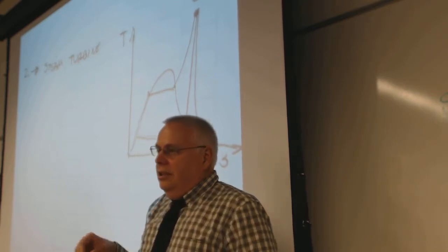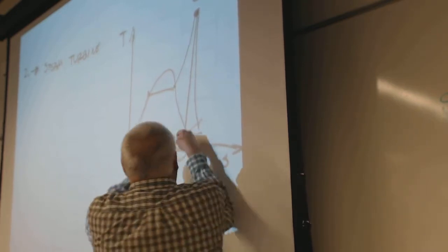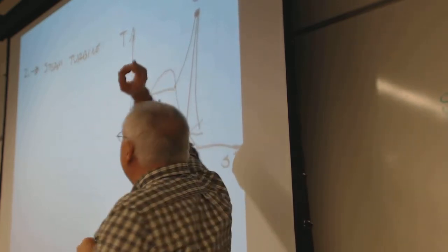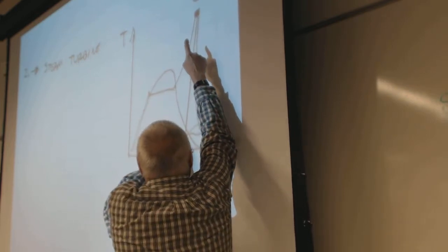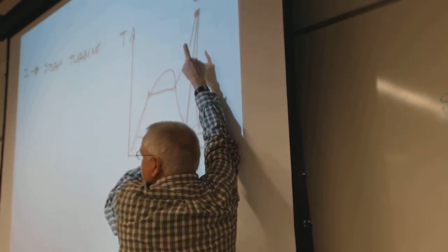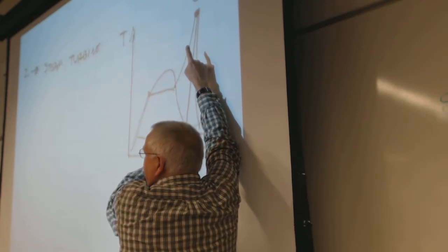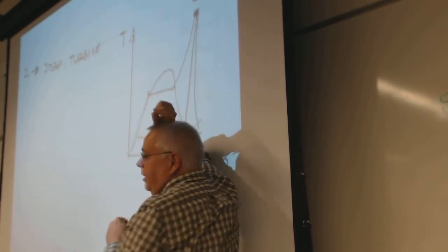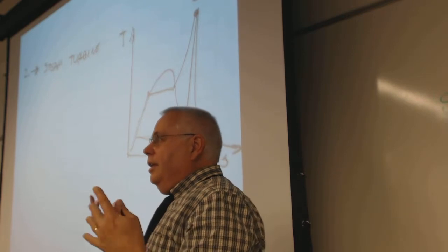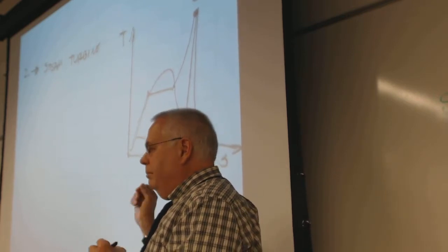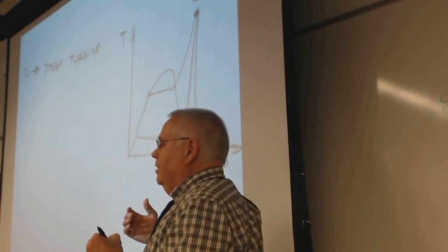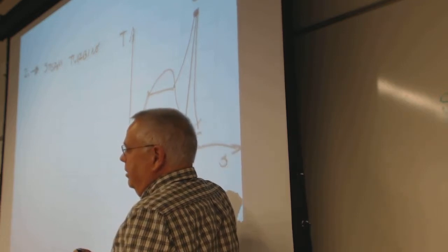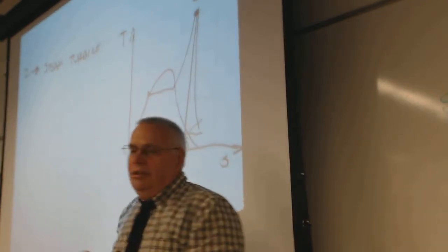And then if I have a process that has an isentropic efficiency, this is the amount of the difference in enthalpy, which is all we ever really care about. Enthalpy there to the enthalpy when we find this state. Using entropy, we find the state, and then knowing that state, we find the enthalpy value for it. So entropy finds it, enthalpy is what we're looking for. That's the total amount of energy available to be converted. If we discovered by testing that it converted 90% of that energy to work, then that's a 0.9 isentropic efficiency.